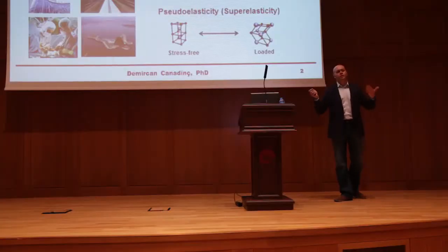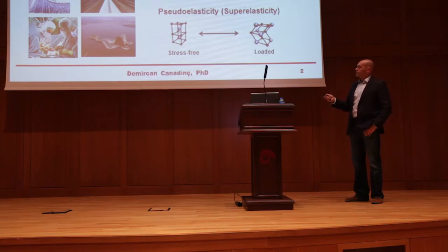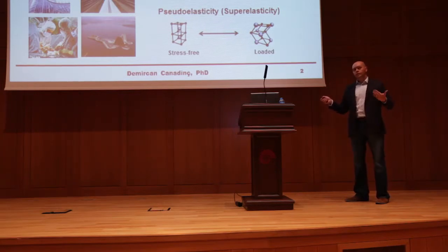There is another property of these materials, which is the so-called pseudo elasticity or super elasticity. It's not elastic, but it is like elasticity. And the thing is that when you apply stress, that is loading, to these materials, then again, due to the unstable energy level, the material changes its microstructure, and in the loaded case, it has a different shape.